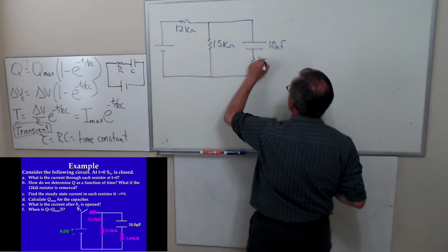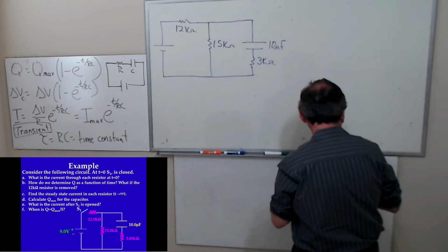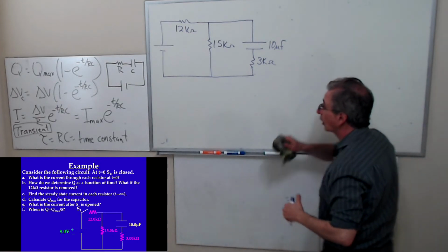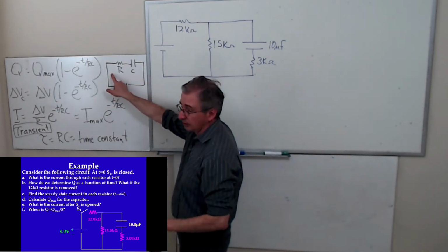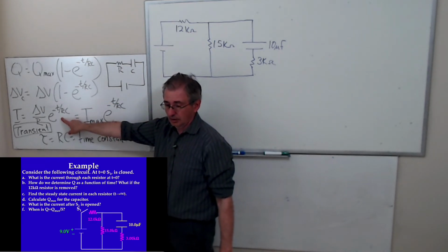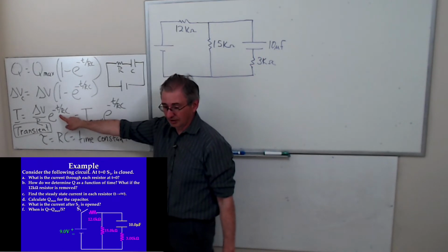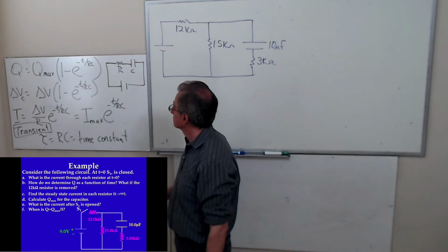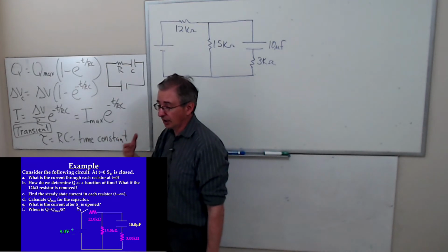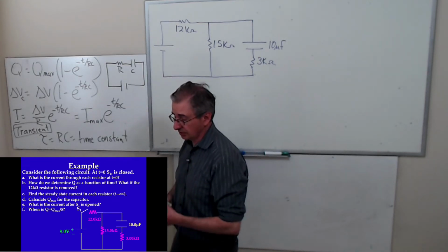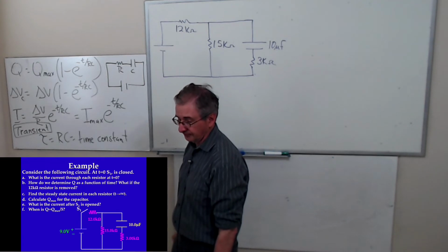But I thought a capacitor acted like a wire after it was fully charged, like t equals infinity. No, because when this is fully charged, the current's 0, right? Put infinity in this exponent. Yeah, but is there current on either side of the capacitor? Yeah, but there's no charge going on the plates or leaving the plates at t equals infinity, when it's fully charged. Yeah.